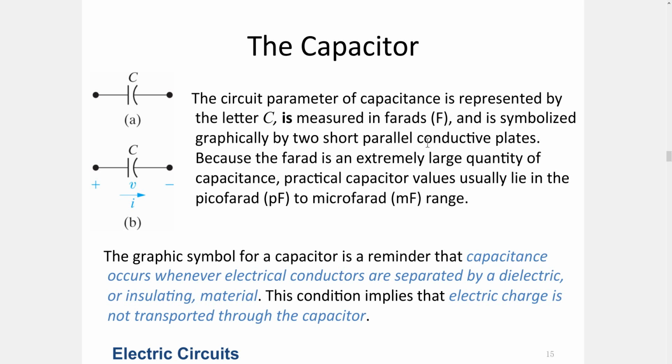So the capacitor only conducts current when the voltage across it changes, and the direction of the current when this happens follows the voltage polarity, from a positive potential to a negative potential. This potential difference is the voltage, and as we know, the current flows from higher potential to lower potential. So the reference direction is chosen like this.